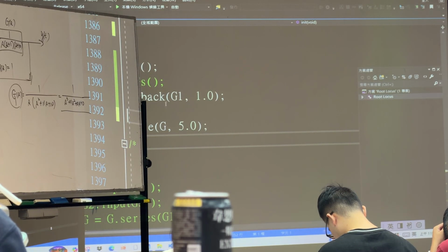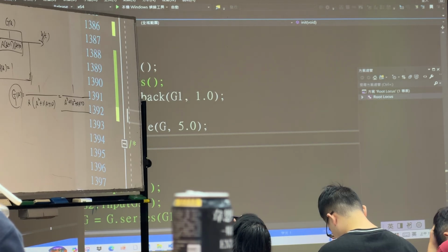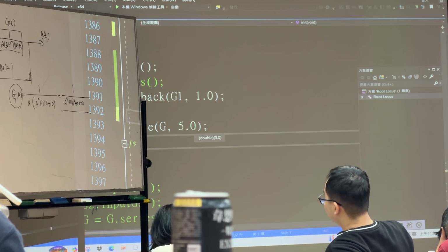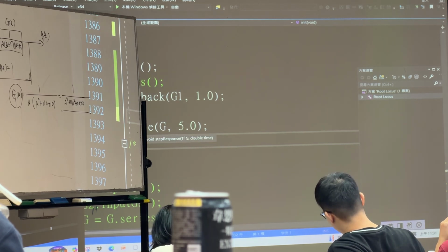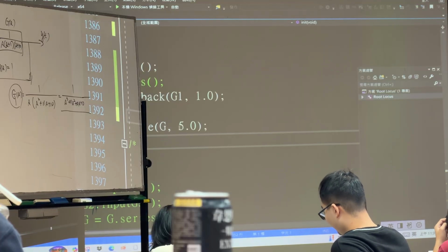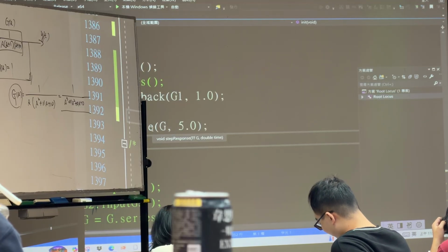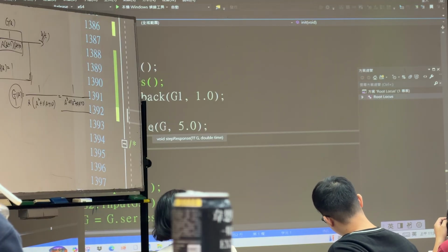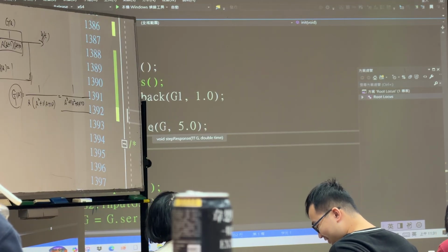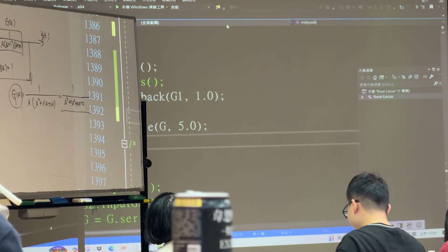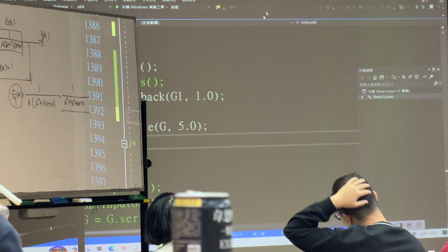And then we will generate the output, and we'll take a look at the step response for 5 seconds. The step response, as I explained, you can use the Euler method to solve, right? 你可以用教过的那个流拉法，对不对？来解 step response. Okay. So let's take a look at this one.